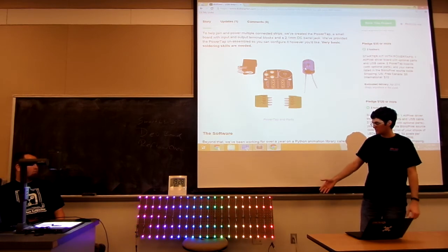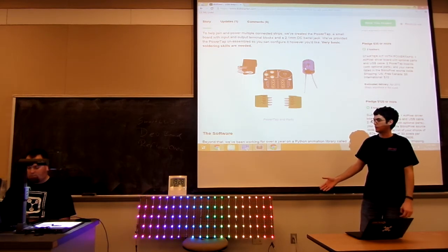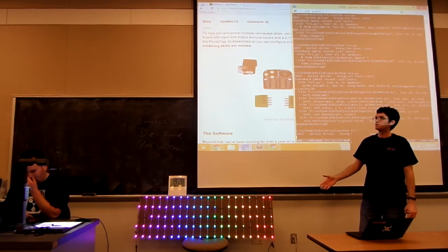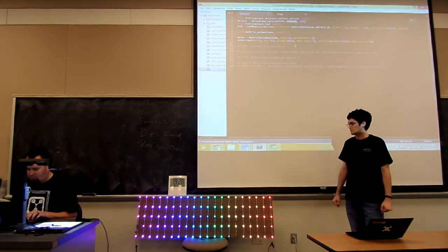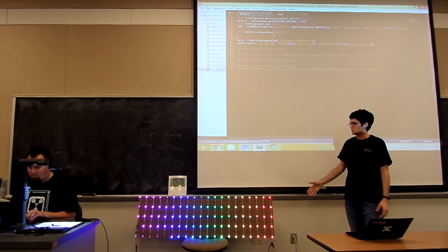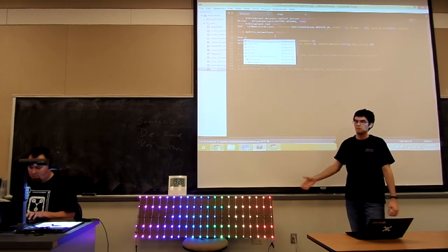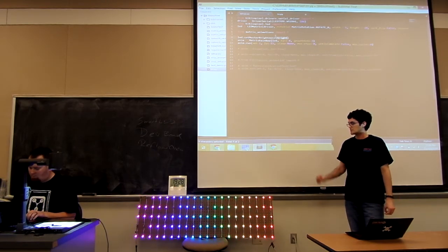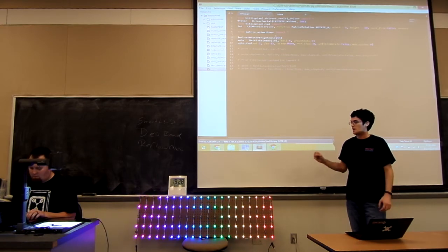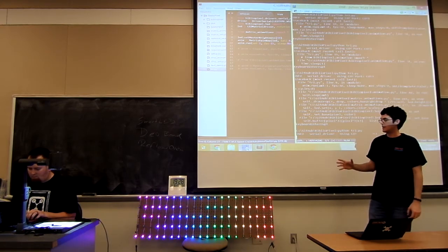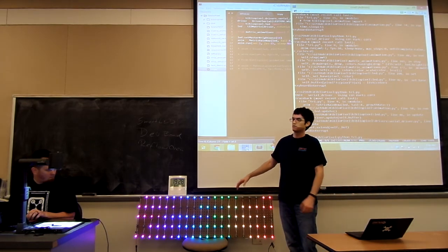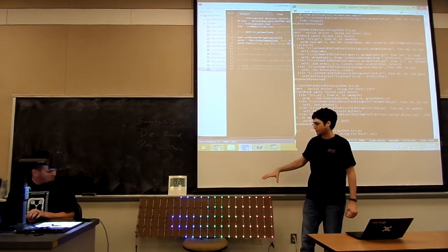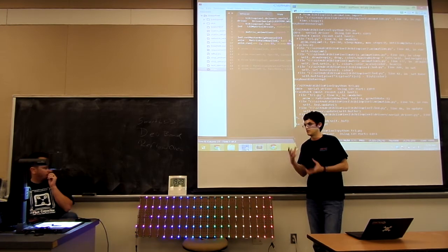So this right here, based on my testing, is probably pulling between 800 milliamps to an amp of power for 100 of these, decent brightness, nice rainbow animation going. If you were to send all of these to maximum brightness, full white, what you would actually see is towards the middle, because of the current draw, your voltage would drop a little bit, and they would actually turn pink because of the loss of voltage.